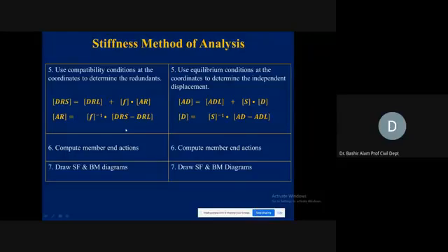And similarly, the rearranged equation you can see, instead of AR, now we are finding out the displacement. Instead of inverse of the flexibility, we have inverse of the stiffness coefficient matrix. Instead of the DRS, which was a precondition, now we have a precondition AD, action corresponding to the displaceable joint we will be looking. Instead of the DRL, we will be looking now again action corresponding to this displaceable joint in the actual loaded structure. So this is the equation.